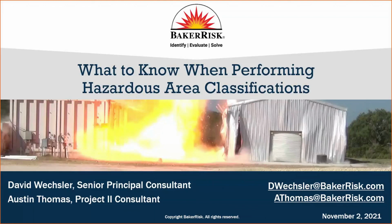You may also want to do a hazardous area classification evaluation when you're looking at a means of control, such as a hazard condition list, or a change of work that's going out there, like a special hazard like welding on pipe or something of that nature. But again, I'd like to see it done at least annually. I would prefer quarterly, but most definitely every time you do a management of change process.